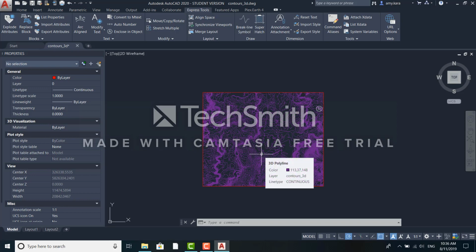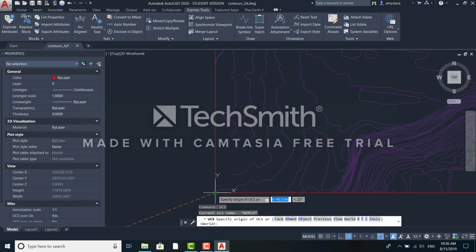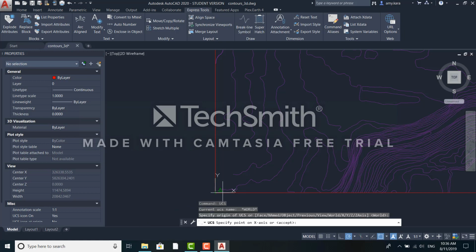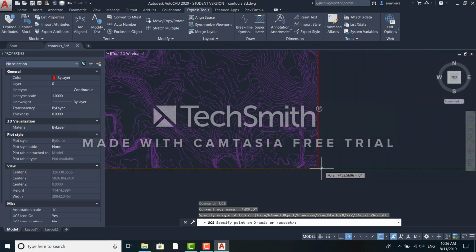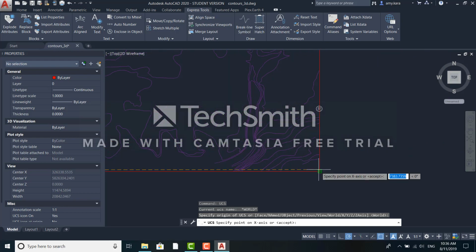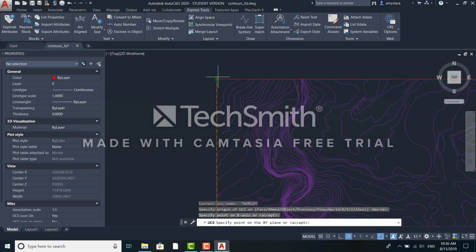So to do this, we're going to type in UCS and then press enter. Then we're going to select the corner of our rectangle that we've created, and then we're going to select and drag and then click along the x-axis in order to specify this point, and then we're going to do the same for the y.